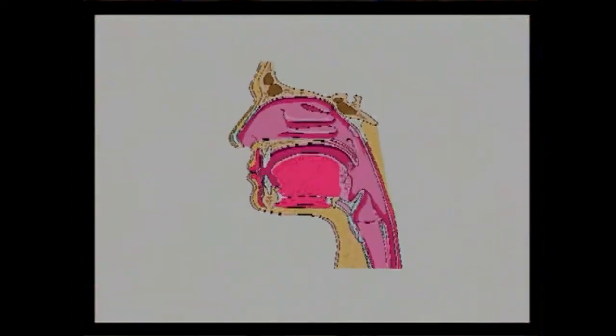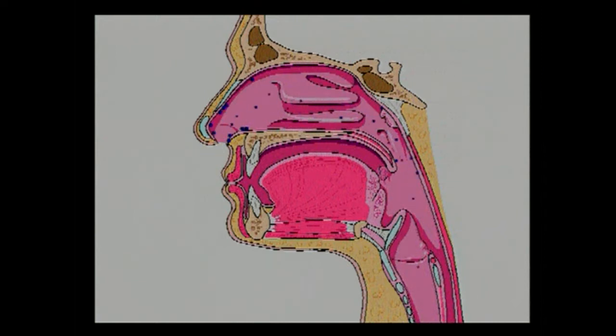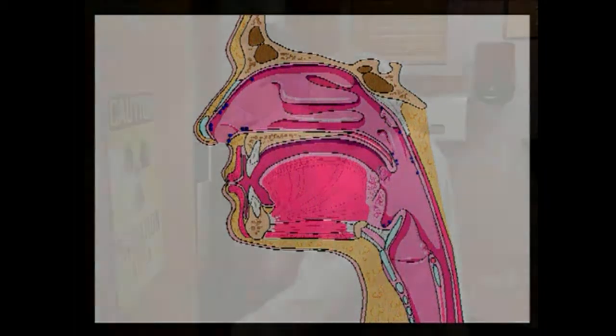Excessive exposures to dust can produce a lung disease called pneumoconiosis. For silica dust exposures, the specific type of pneumoconiosis is called silicosis. Silicosis is caused by the lung's retention of very small-sized particles of quartz. Larger particles are removed by the body's defense mechanisms, found in the nose and throat. Our sampling device only allows small particles to be collected. We will discuss that later.